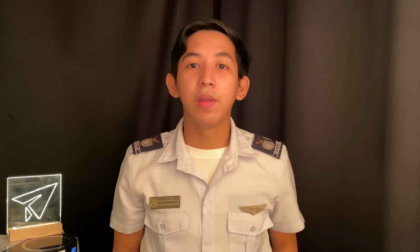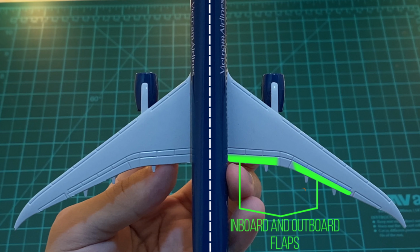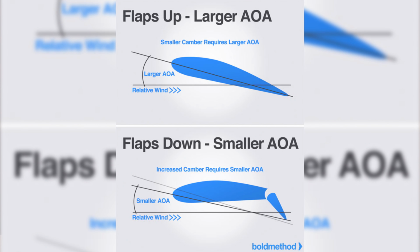For the secondary flight control surfaces, we can classify them into flaps, tabs, spoilers, and slats. Now remember that not all of these have to be present on an aircraft. An aircraft may possess one or at least a combination of two secondary flight control surfaces. Flaps are one of the most common on aircraft and are usually located inboard at the trailing edge of the wing. Flaps are lowered to increase camber of the wing for greater lift and slower flight. This allows control at lower speeds for short-field takeoffs and landings.